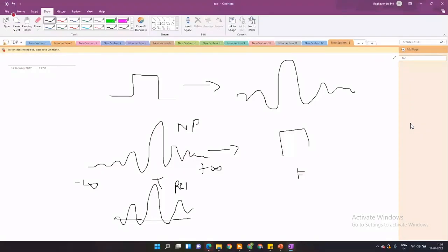raised cosine pulse, RCP, and the pulse in the frequency domain doesn't look like an exact square. It's similar to a square. You have a little bit of sliding over here, a small amount of angle that's present, but that's okay because you're not actually going beyond the limit that is set for you. So we shape our signal in that format so that, one, intersymbol interference doesn't happen, and two, we don't go beyond the limit that is set for us.